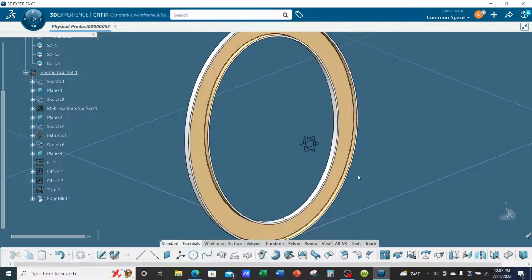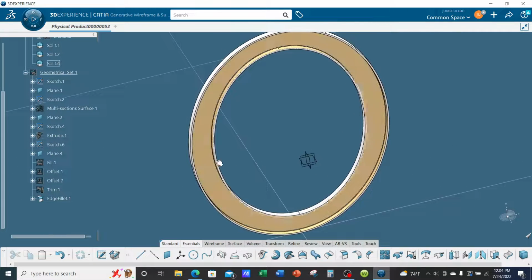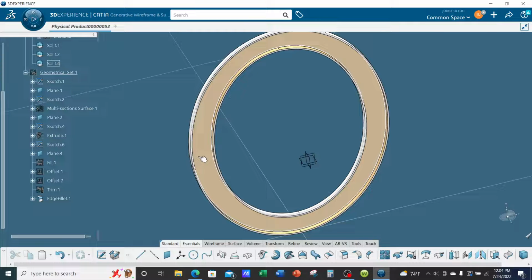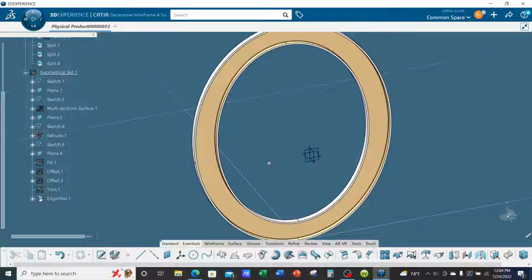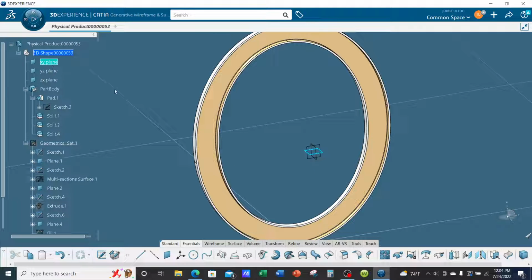But they tell you, hey, we're going to make the lower portion of the web and the flanges, instead of 1/2 inch, 3/8 of an inch, 0.375 inches. Okay, so we're going to thin this out even more. All right, so we're going to first create a rectangular surface going across, and we'll start thinning out the web and the flanges from here to here. And we're just going to use our existing plane, which is the XY plane.